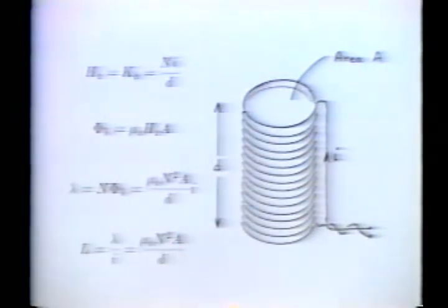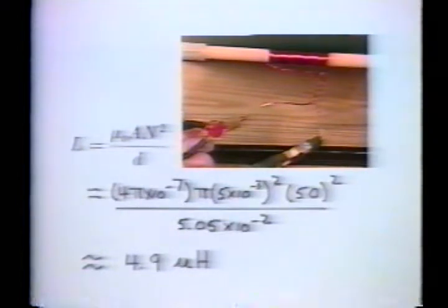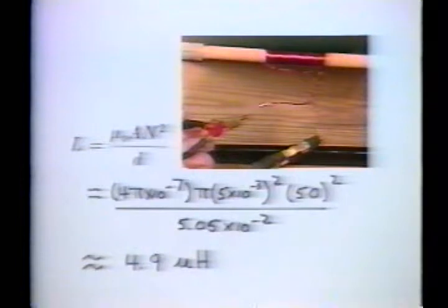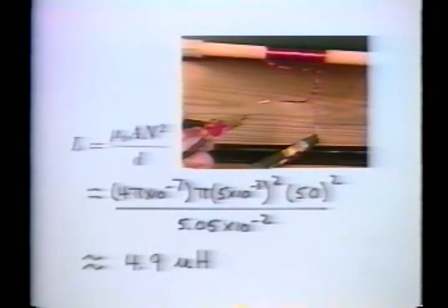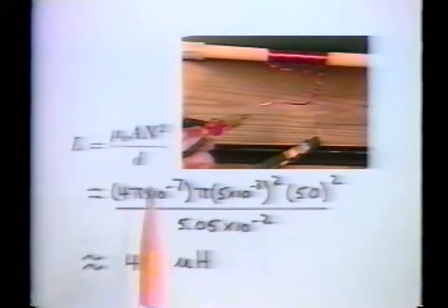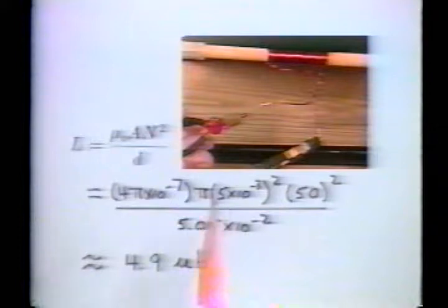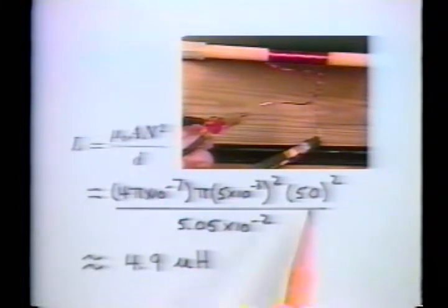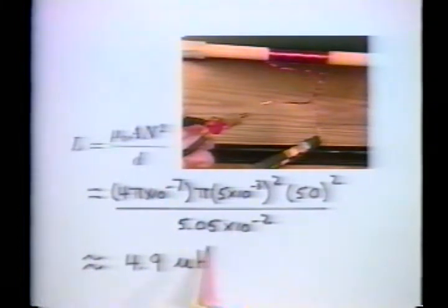The inductance meter measures the coil inductance at 1 kilohertz. This frequency is high enough that the coil inductive reactance greatly exceeds the small coil resistance, which we have neglected in our analysis. We measure 5.9 microhenries. This inductance has contributions from the coil and connecting wires.